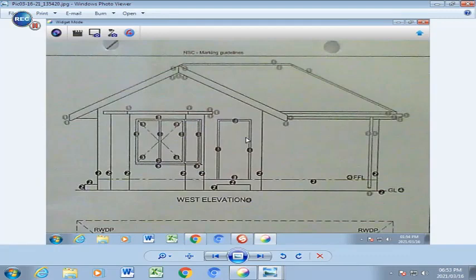You're also going to find significantly that these parts of your barge boards go slightly further than the required roof finish that we have there. But that is the purpose of a barge board. It covers slightly further than the fascia board. So if this will not align with that specific end there, it will probably end right here with that end point of your fascia returning on that side, and the same here with that one returning on that side there.